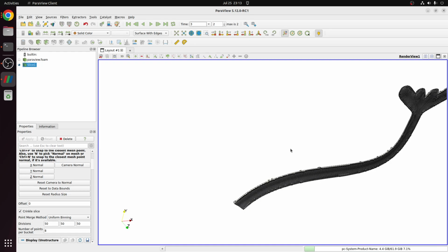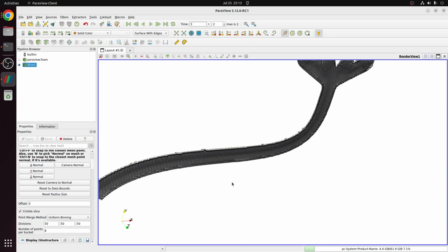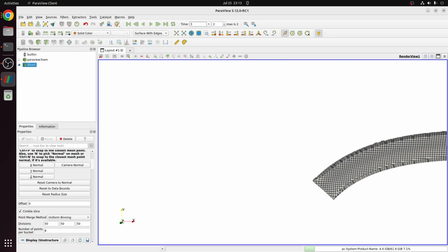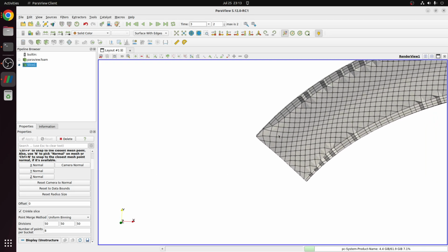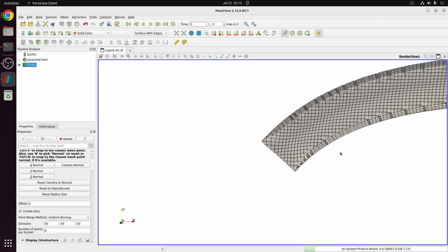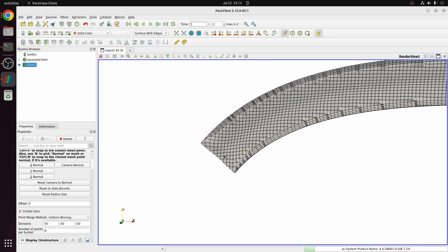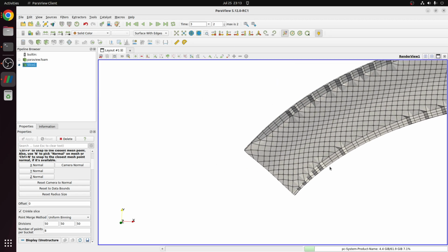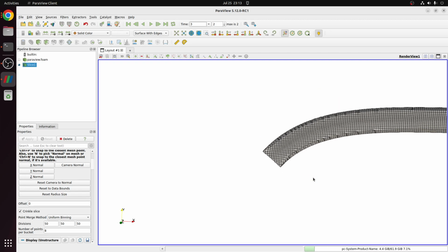So why did it fail there? It is not some very complicated stuff there. The thing is, if it wants to put boundary layer mesh at 90-degree angles, it will result in poor cell quality, and that's why sometimes it just avoids it. And it is mostly irrelevant there, I mean, closer to the outlet.